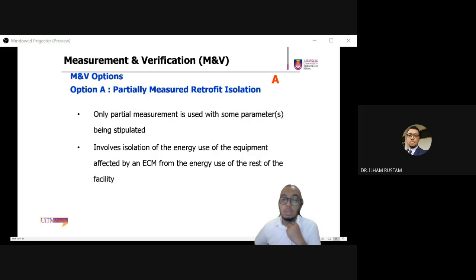Typically people will install a flow meter at the time they first install the machine, not during, let's say, when you only now want to implement energy saving. The machine has been there for years, and you want to measure, so you can't simply shut down the machine and install a flow meter. It's going to be very hard.